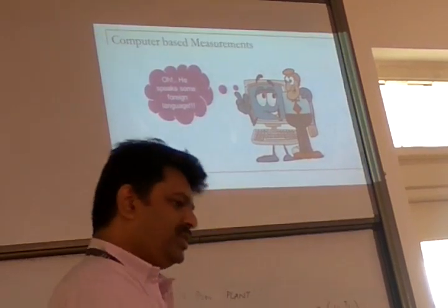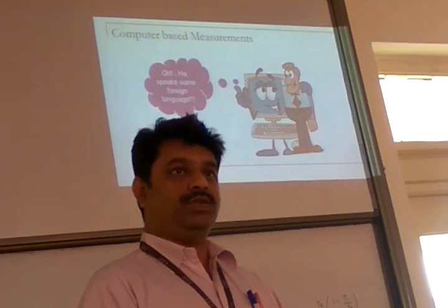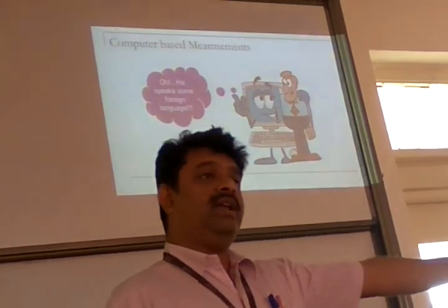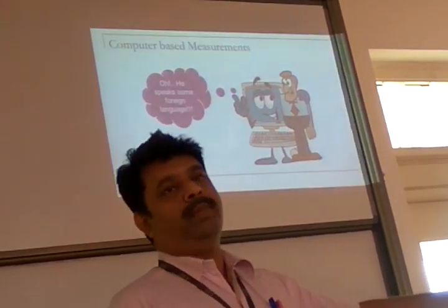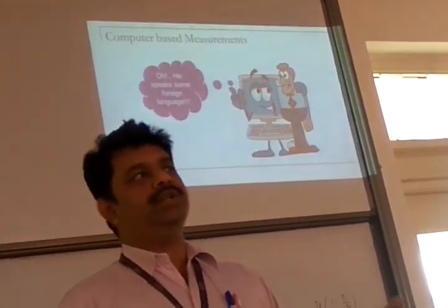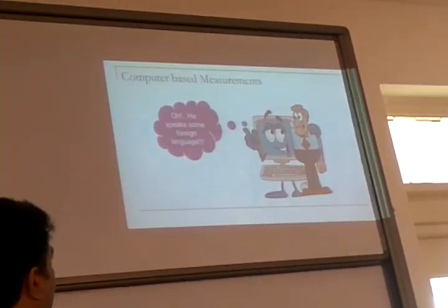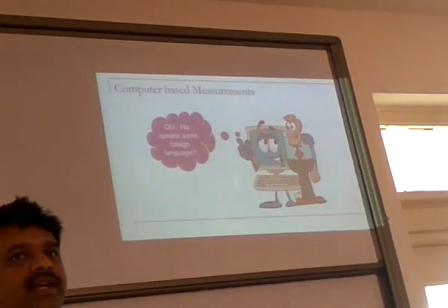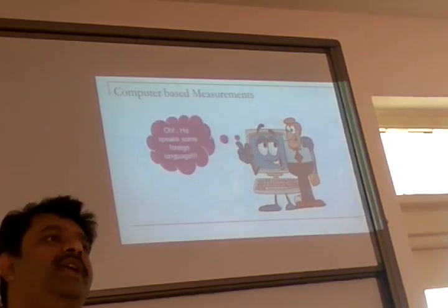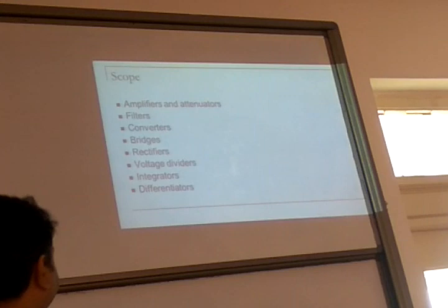Then this has to give some signal. It will give the command in digital. That digital to analog conversion is also needed. Then that analog signal goes and does the control operation to vary the flow. So analog to digital converters and digital to analog converters, both are needed, so that we will be able to take advantage of the computing development in the hardware in the computing industry.